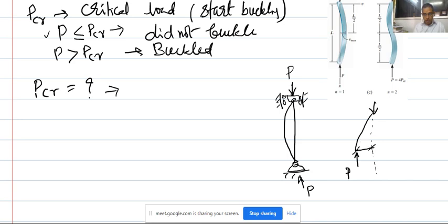Now, this has got deformed, and at a distance x from one end, the displacement, let us say V, or Y also does not matter, let us say Y. Let us say the displacement at distance x is Y. Now, if you look carefully at this particular member at this point, I am talking about the previous diagram, I am applying load P here, and at this particular point there is a P load, but apart from the P load, because this has got deformed some amount, it has got a moment also, which is M, right, very important.